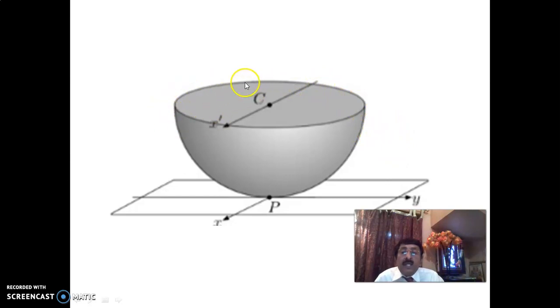This is the hemisphere. This top circle will look like an ellipse in isometric, and every ellipse will be enclosed in an iso square. If it is 60, we'll enclose it in a 60 iso square, and finally convert by multiplying by 0.816. Okay, this is the circle. If it is 50 diameter, we draw a 50 square, and finally convert into iso.